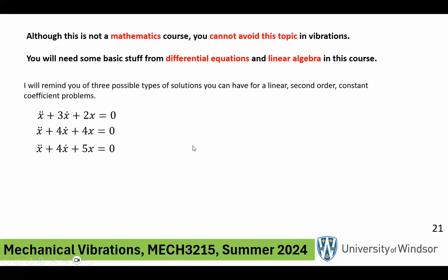Why are these important to us? Because at the end of the day, we are dealing with a dynamics subject. It's Newton's law applied, force equal to mass times acceleration. What is the acceleration? It's x double dot, the second derivative of position, for example. So F equals m x double dot. Where is the F? In this case, it's a free vibration, so the force is zero, but it doesn't have to be.